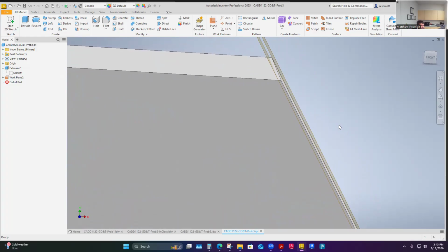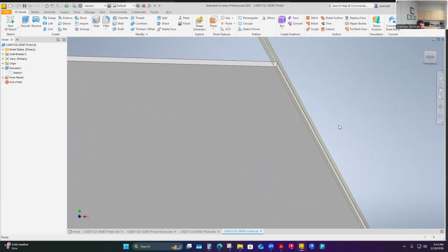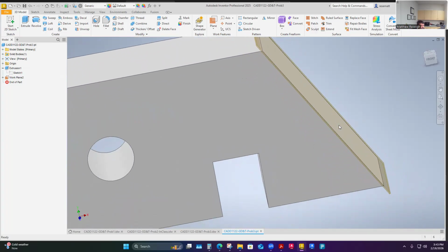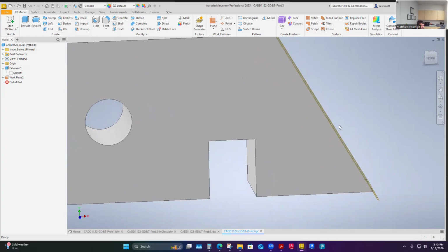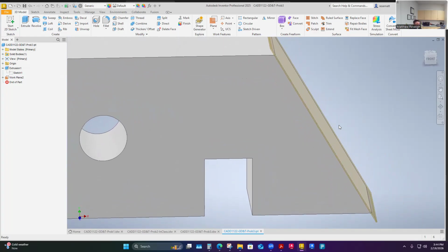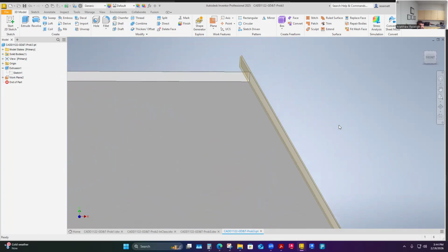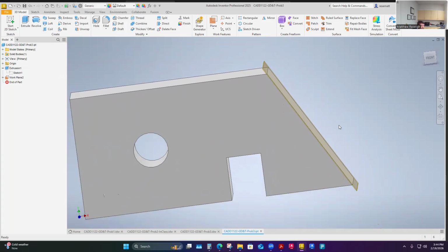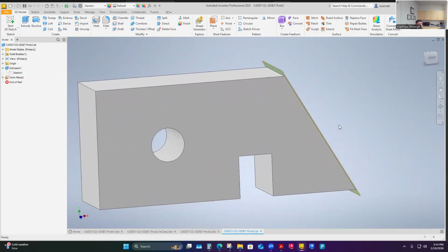So I'm just requiring that it stays within that envelope. If it varies a little bit, as long as it doesn't go one way or the other beyond this 10,000ths tolerance zone, it's an acceptable part. If it deviates away from that, then it's a rejectable part. So that's how I'd interpret what's going on there.